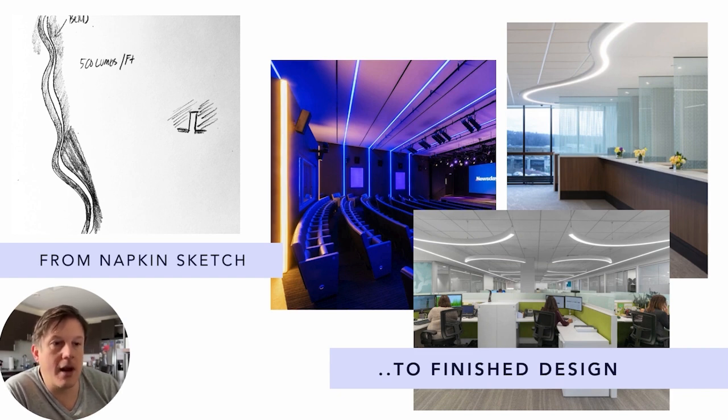So if you're saying, I want a curve that's going to match the curve of the ceiling where the ceiling meets the ACT ceiling, great, sketch it out for us. We can curve these profiles to within a 10-inch radius, which is really tight for a big piece of metal like that. Continuous lensing, so you don't have any weird bright spots or any kind of shadowing of LEDs. It's really easy to do this stuff with Day-O-Lite.